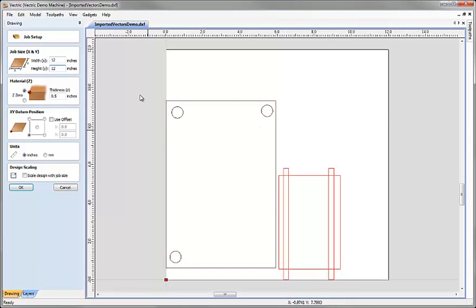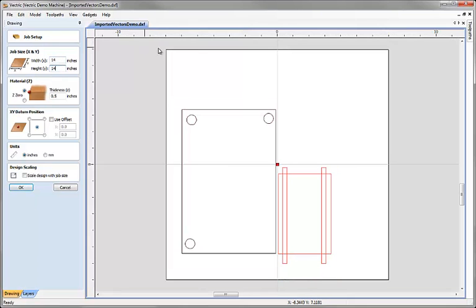We can modify how we add that material, in fact, by just changing where we stick the origin. So if we have the origin or the datum position in the middle of the block and we were to extend again, we would find that it's going to add the dimensions evenly as a border around our image. Having added the border around the image like that, we can always go back and set the datum position. So effectively the datum position can be used temporarily while you're in this form to decide where you want to add the extra material.